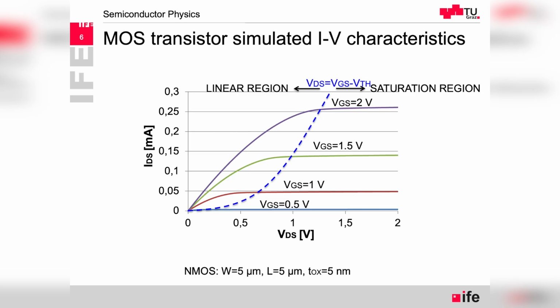What I would like to discuss in the next slide is that we can make some approximation about the on resistance, that actually for very low VDS currents, we can also think about it as an almost linear dependency. Here I would like to stop just for a good reminder on the border between the linear and saturation region.